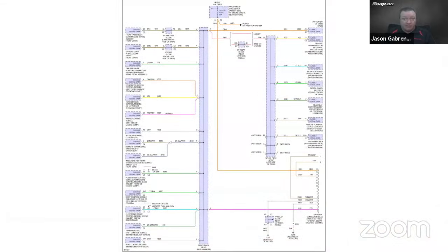So we have a wiring diagram here. On this vehicle, it was a GMC truck, and it used a single wire protocol off pin 2 there. And also on this vehicle, and it's not just GMs, many vehicles have this style of network. They call it a star style of network.